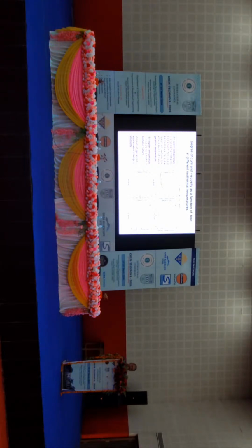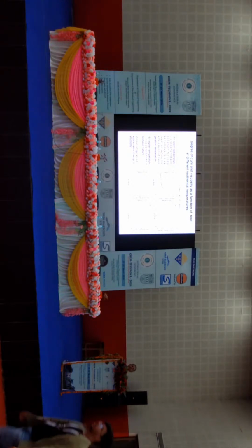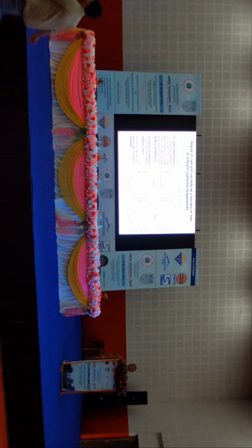So as I told earlier, the liquid resin undergoes first a gel state and later a rigid solid state. In industrial practice, we have to complete the mold filling within 50% of the gelation time, because once gelation occurs, the viscosity shoots up exponentially. This viscosity model is required only for mold filling, and the mold filling has to be completed within 50% of gelation time. So if I can model the viscosity variation within 50% of gelation time, that's more than enough. That's what we are going to do.